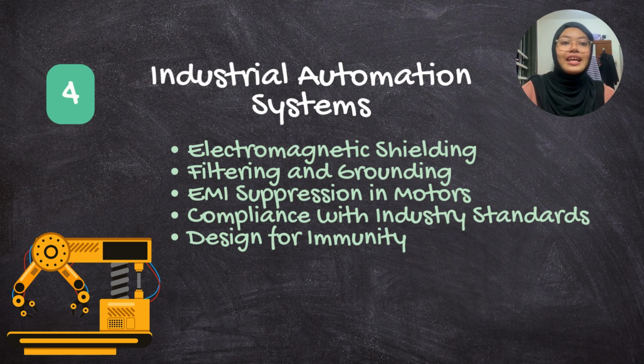Compliance with standards like IEC 61000-6-4 and IEC 61000-6-2 ensures systems meet emission and immunity requirements. Designing for immunity ensures these systems remain reliable and safe, even in high-EMI industrial environments.